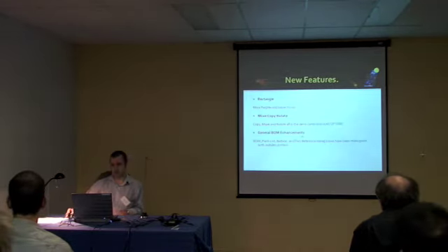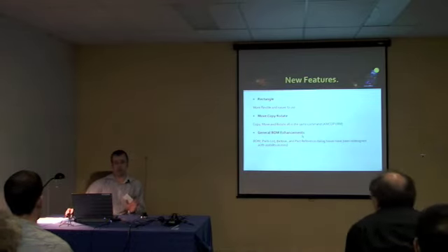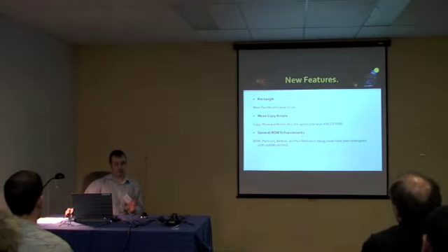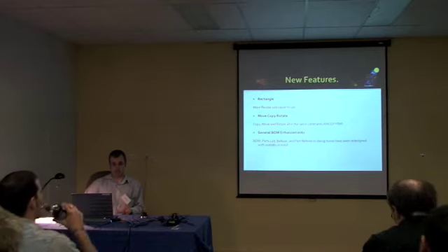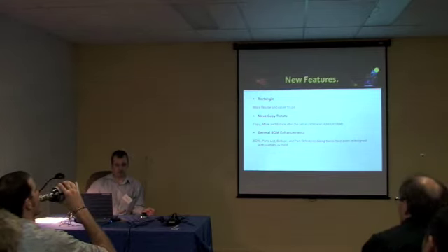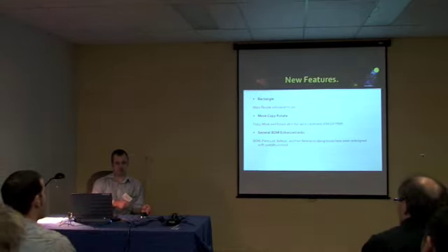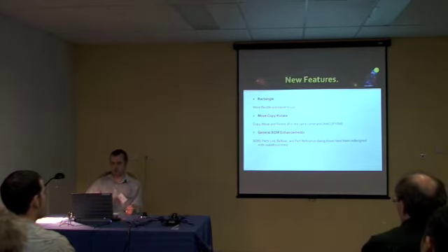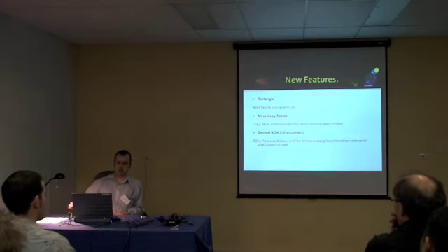General BOM enhancements, so your bill of materials. These only appear if you're using structure. Again, you look at the model, look at a spreadsheet, and transfer from the model to the spreadsheet. If you use structure with parts and assemblies, the bill of materials takes care of itself, so the parts list automatically updates.